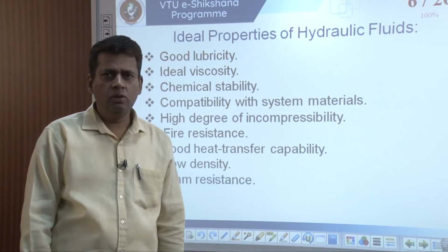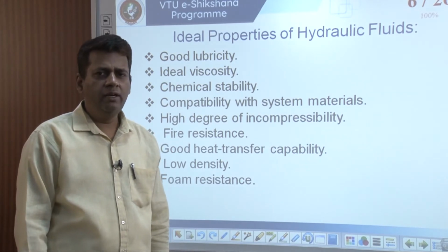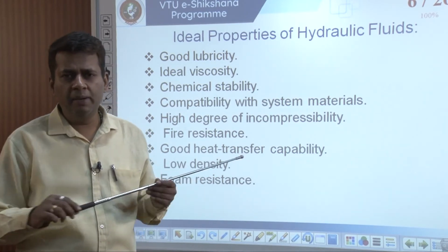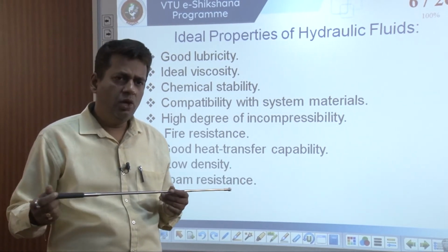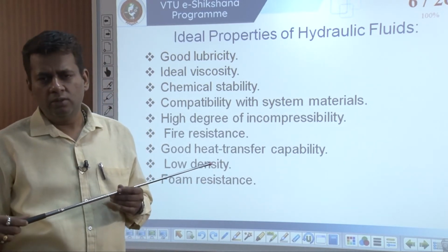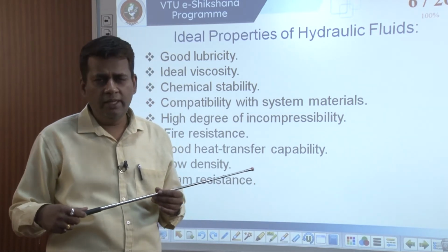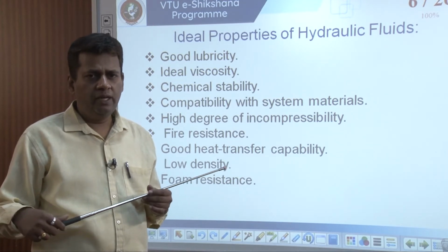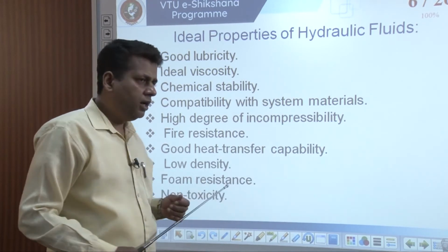Foam resistance. So, foam is formed by interaction of hydraulic fluid with the rubbing surfaces. So, we have found that whenever there is rubbing between these two mating surfaces, foam is created because of the churning action of the hydraulic fluid. So, this is unwarranted. So, the foam will form sludge on the top or the bottom surface and it needs to be expelled out frequently. Non-toxicity.